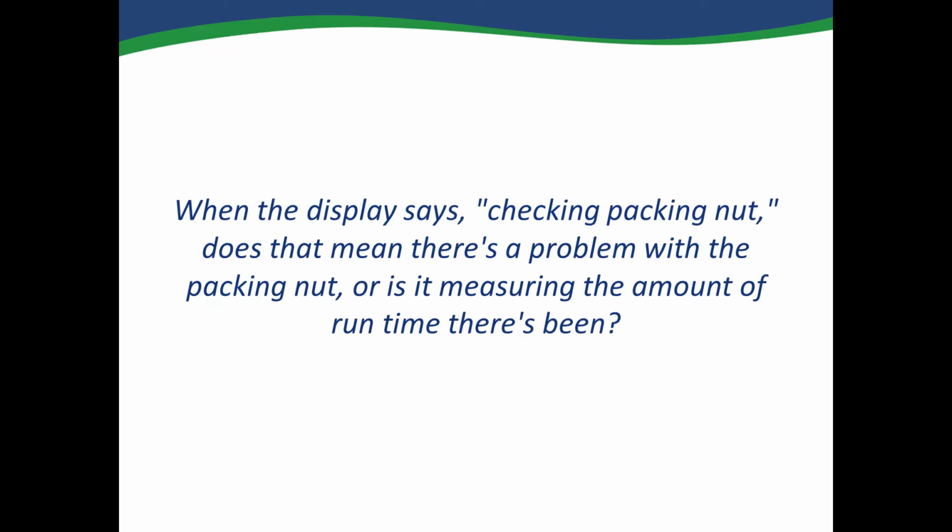No, it doesn't mean that there's a problem with the packing nut. Basically we run a timer on the A2000, just letting you know that this is the typical time that you need to adjust your packing nut. Typically, you won't even see a leak at this time, but it's just a reminder that you should check your packing, and you don't have to do it immediately. Within a day or two is what would be the best timing.